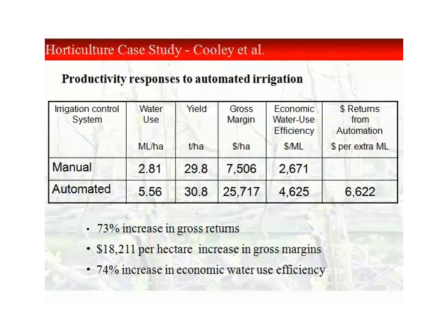We were able to establish in this experiment a 74% increase in economic water use efficiency for this year. It should be noted, on commencement of this experiment, we determined relationships between plant water status and soil moisture on this site, and therefore we were able to set very accurate maximum and minimum soil moisture depletion levels.